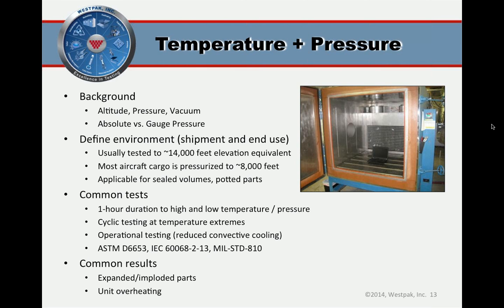So with this, it's very important to define in your test plan, and when you're reading test standards, are you talking about absolute pressure or gauge pressure? So absolute pressure, right now, where we are, is 14.7 psi, but the gauge pressure would be 0 psi, because gauge would refer to the difference over atmosphere. So make sure those are defined. Obviously, if they are confused or mixed up, you can have an unintended, either overly severe or overly mild test.